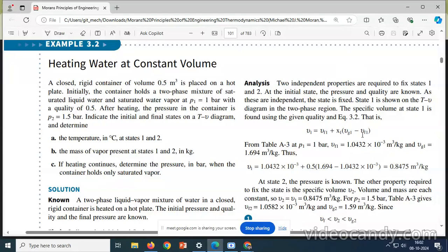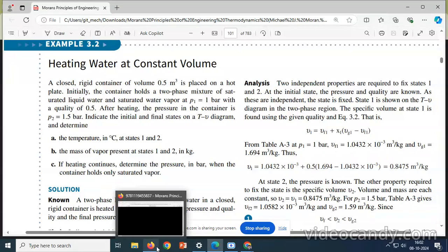That is the specific volume per kg. How much is the specific volume when the water particles are in liquid state? This is the equation they have written. So we need to find this from table A3, or you can go to the steam tables and find the standard values of vf1 and vg1, taking pressure at 1 bar. Using these values, now I'll go to that table A3.